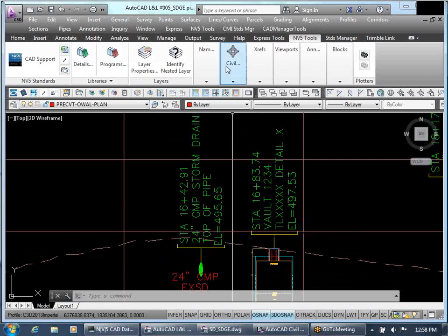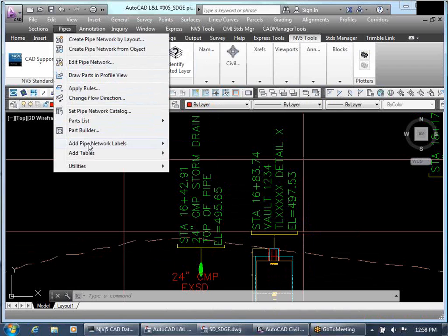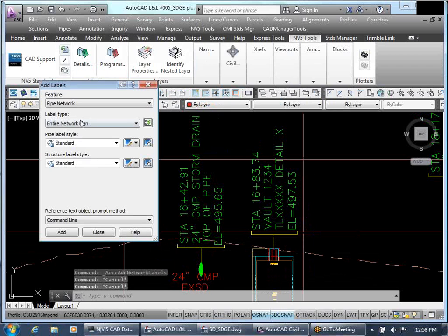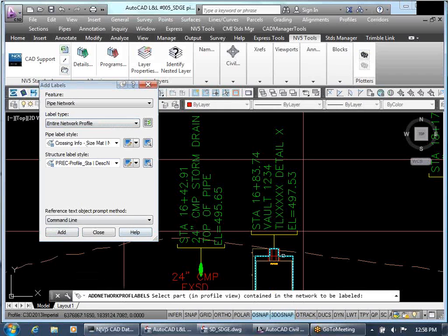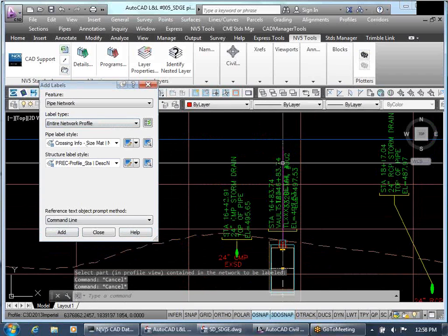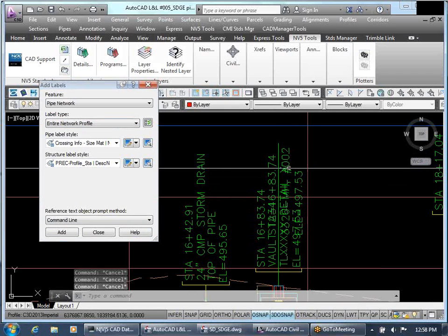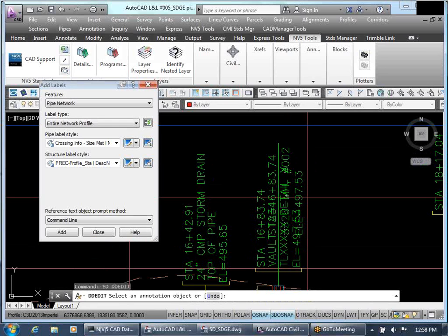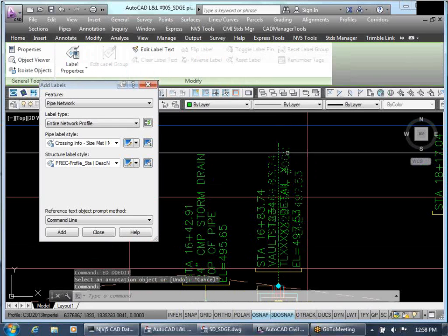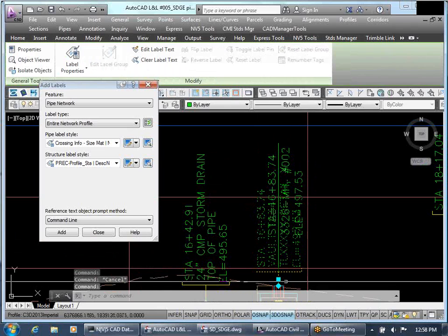You can also keep that pipe network label on there. You may not want to delete it like I did. You may want to keep that information there so that you know what number it is, if you label your parts correctly. Then you can go in here and just change it to match what you did on your pipe network label.